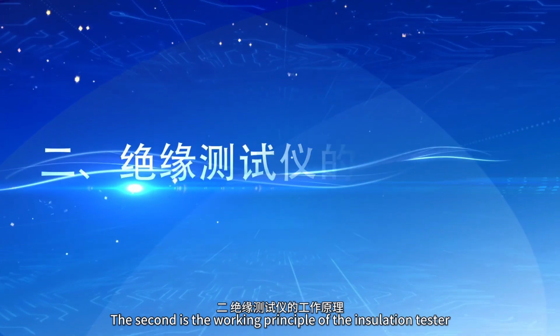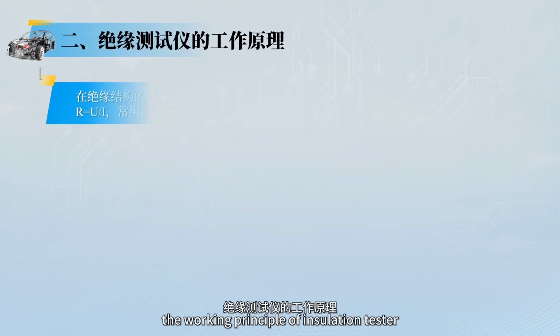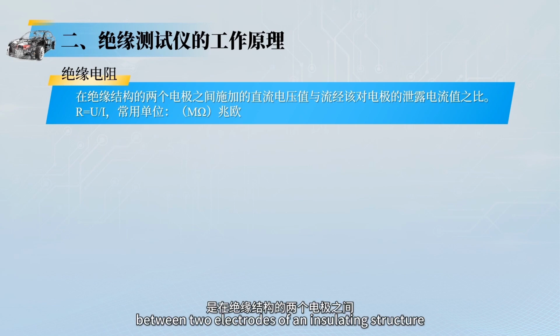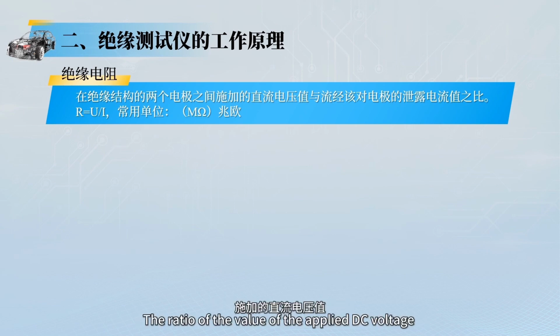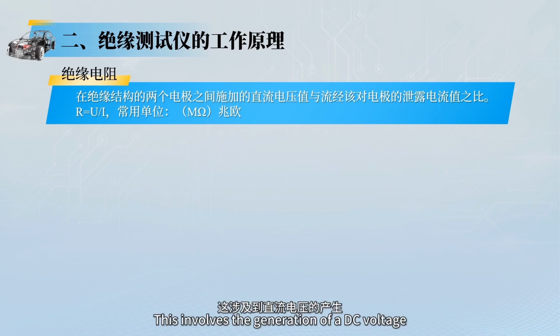The second is the working principle of the insulation tester. Let's first understand the working principle of insulation tester. Insulation resistance is defined between two electrodes of an insulating structure. The ratio of the value of the applied DC voltage to the value of the leakage current flowing through the pair of electrodes is R equals U divided by I, commonly used in megohms. This involves the generation of a DC voltage.